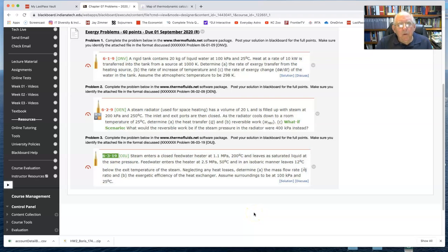Okay, in this particular video, we are going to now finish the final of the three Exergy problems. This particular problem is a closed feed water heater consisting of two streams. Both are water or steam. The first stream is coming in at 1.1 megapascals and 200 Celsius, and it leaves as a saturated liquid at the same pressure. And then the other stream is feed water that comes in at 2.5 megapascals and 50 degrees Celsius.